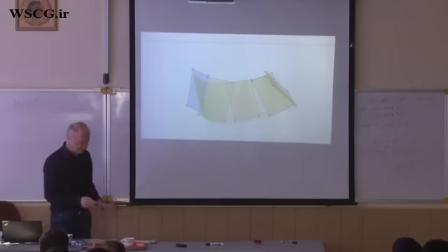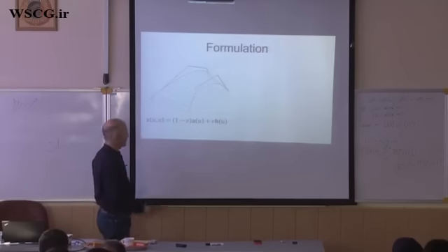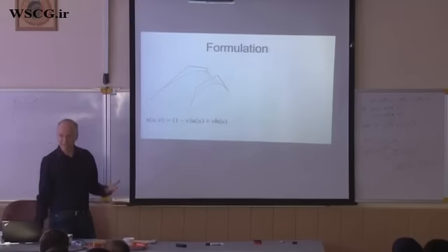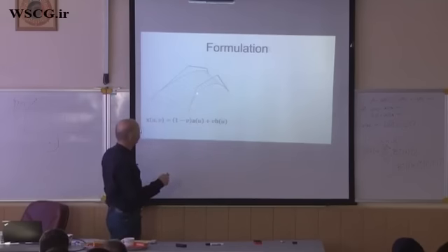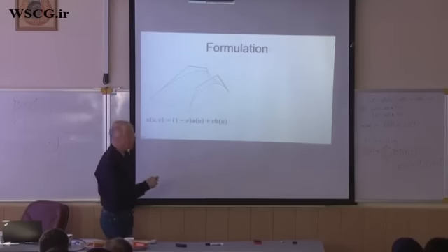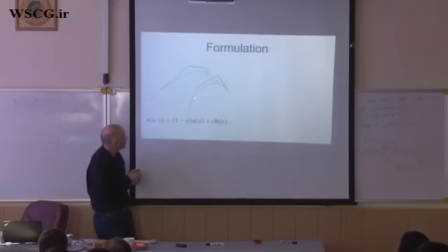So what then my student did, he says, I want to have my surface as a standard Bezier surface. I explain it with Bezier, but we can do with spline as well. So you have here a cubic Bezier curve, here a cubic Bezier curve. You connect, so this is the Bezier curve A of U. The next is the Bezier curve B of U. The connecting line is, of course, (1 minus V) A plus V B. This is just a line connecting the curve point A of U with the curve point B of U.